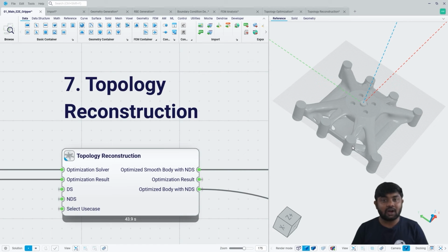So far we have learned how to import the specification sheet, which can contain the materials and the loading information, and we have learned how to create the design space, which is automatically adapted to the different versions of the non-design space geometries, which are 6 and 8 suction cylinders, followed by assembling and performing FEM analysis to see how the part behaves. Later we performed a topology optimization, which is possible using two different kinds of solvers, and then automatically reconstructing the part such that it is ready for additive manufacturing. So at this stage we are basically done achieving the final part.